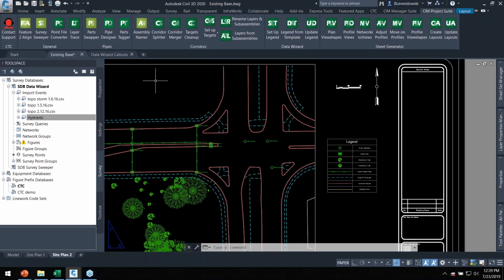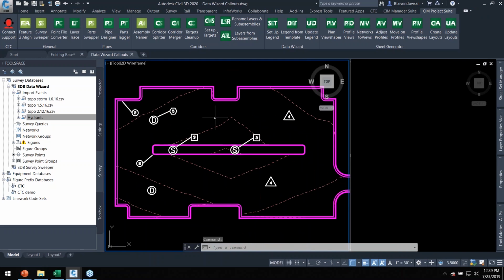Now there's all kinds of objects we can scan for. I thought I'd show you another simple scenario here of creating a legend, and then we'll do a simple quantity takeoff. But it all basically behaves the same way. You've got those first three screens where you choose your source drawings, you choose your object filters, and then you choose what data to extract. And then does it go to Excel or does it go to an AutoCAD table?